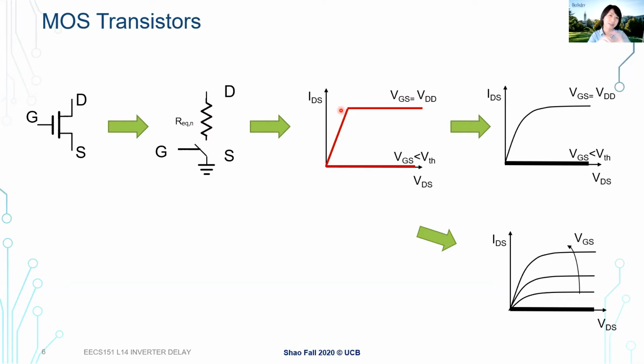You can basically think like the channel is saturated. And then after that, no matter what voltage you apply between those 2 terminals, you always have a fixed current. So this is basically our resistance, or linear, or resistor region. And after that, this becomes our saturation region. Basically, we always have a fixed current, no matter what voltage we apply there. So this is basically the transistor behavior.